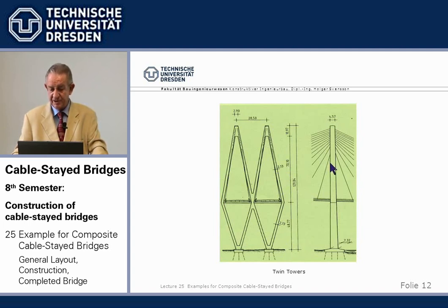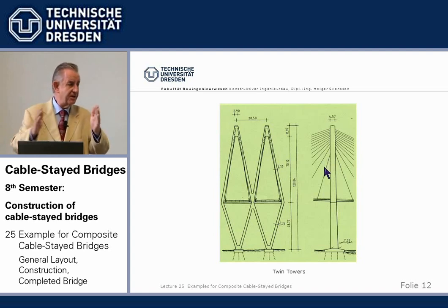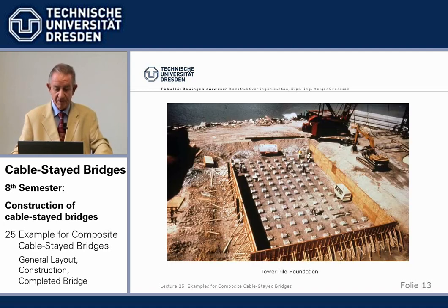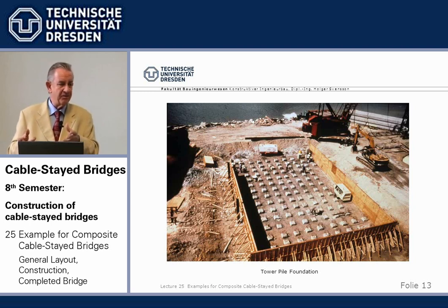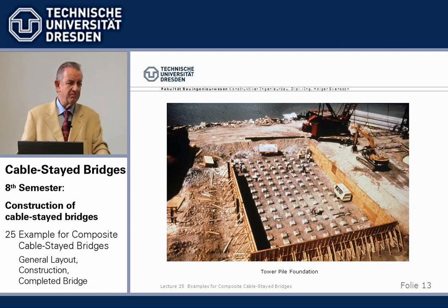In longitudinal direction, we need more width. Already for free cantilevering construction, it acts as a cantilever, it needs some stiffness. Then we are in the Houston area. It's alluvial soils, which means very fine clay and so on, which came in with the water, mud, better said. And the rock is down some 300–400 meters, no way to reach it.